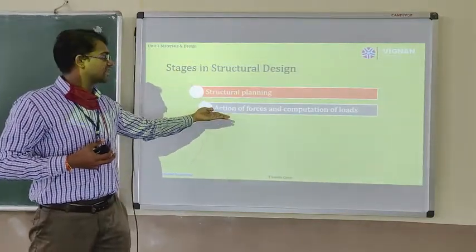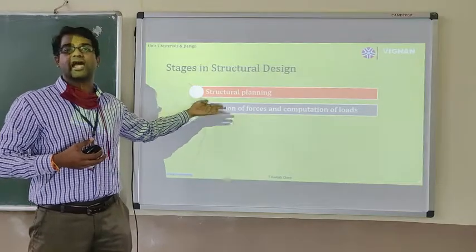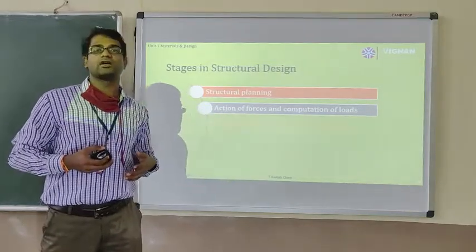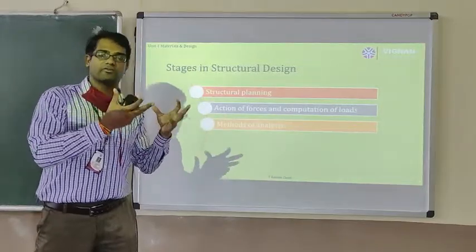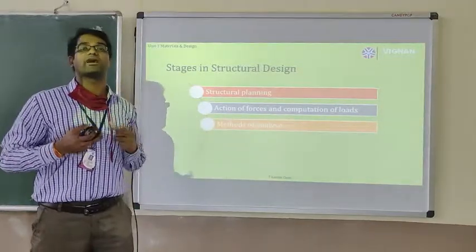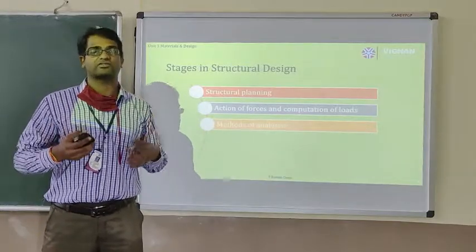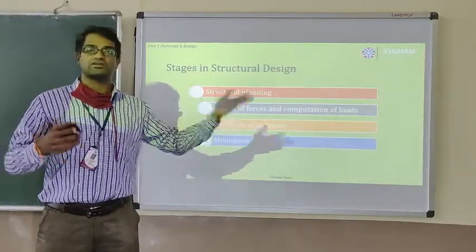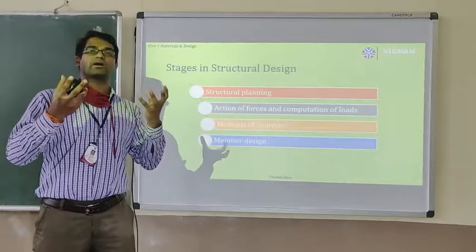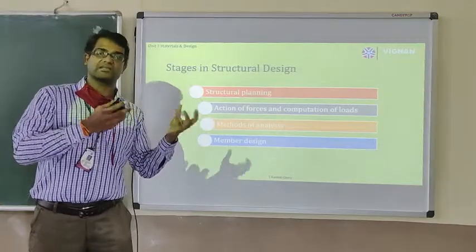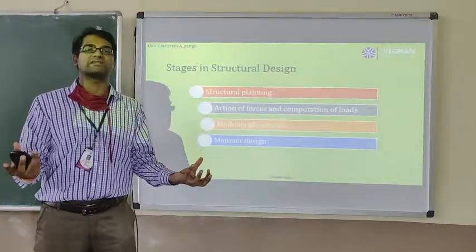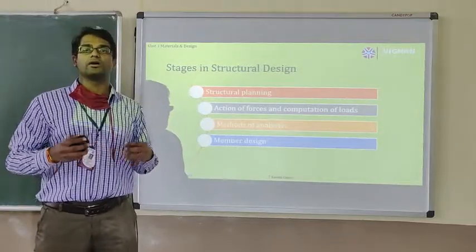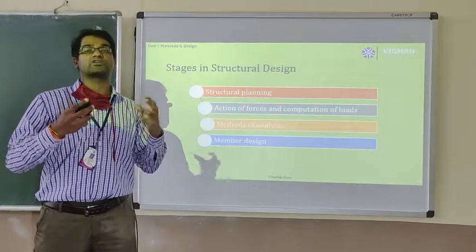Next is the action of forces and the computation of the loads. You need to do that. Next, you need to follow one method of analysis in order to evaluate the bending moments, the shear forces and stresses. For those stresses, you need to pick up materials, RCC, where we have cement concrete and steel, and you need to provide a certain area in order for your structure to be stable.